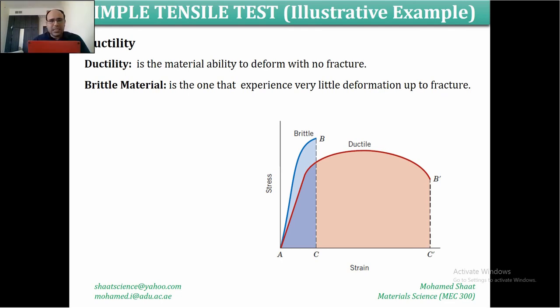Since it is made of glass, if I ask you to bend it, it will be completely fractured. It won't be deformed. Instead it will fracture instantaneously as you try to bend this piece of glass. This indicates that this material has no ductility, zero ductility. A material with no ductility is known as a brittle material. So this is what distinguishes brittleness from ductility, or a brittle material from a ductile material.